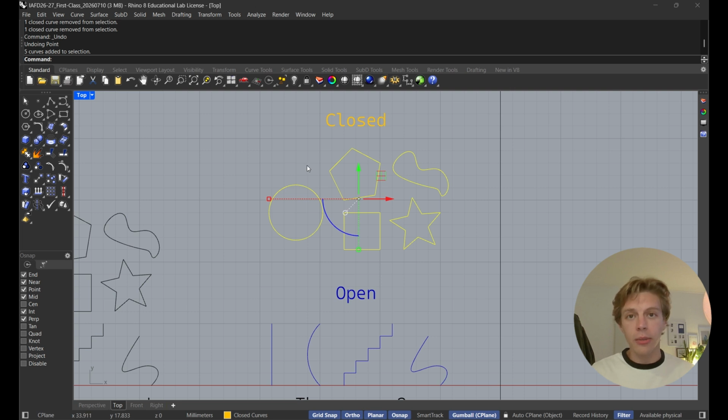And in Rhino, there's actually two kinds of selection boxes. The one that I just showed you is from dragging your mouse from right to left. You see that the outline has this dotted pattern. That means that anything that this box will touch, it's going to select. You see they're all selected.